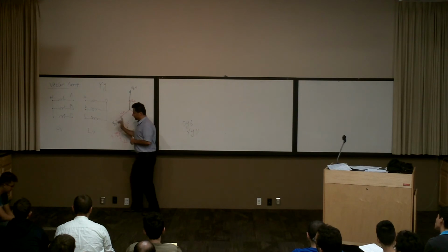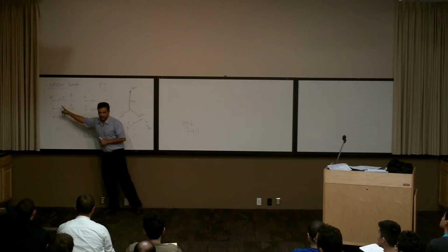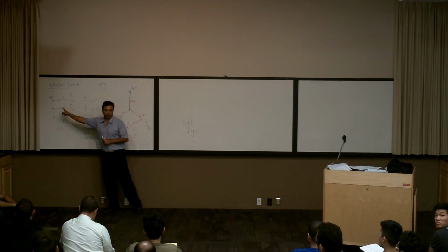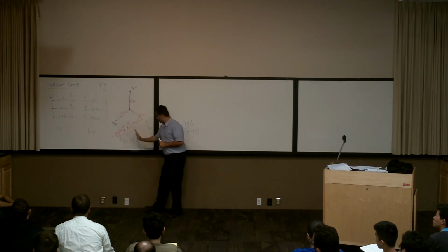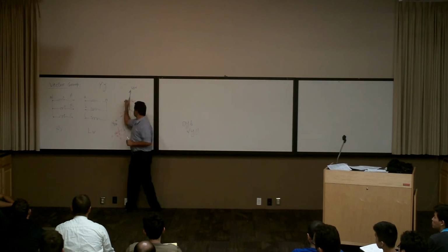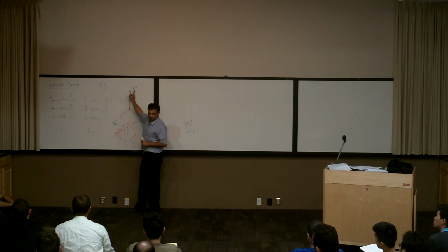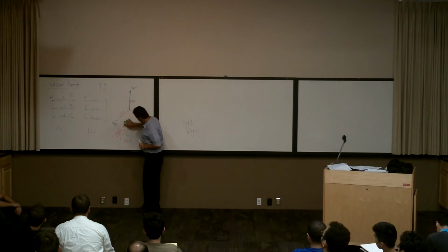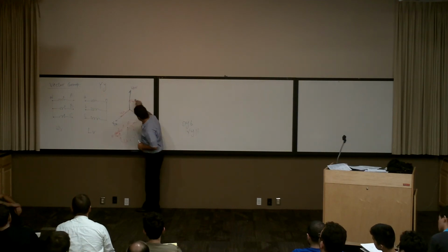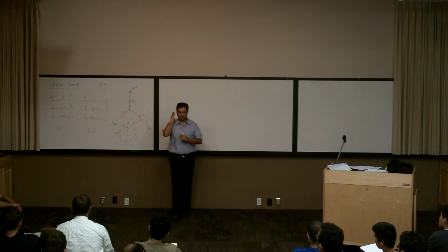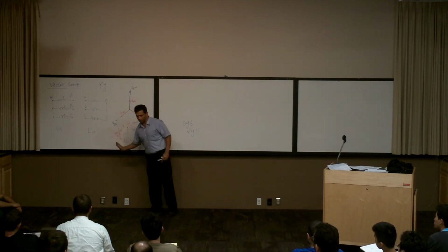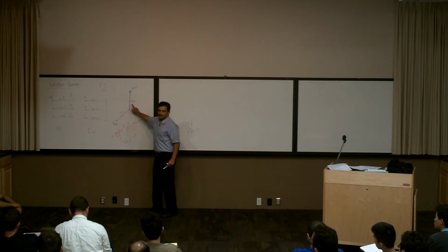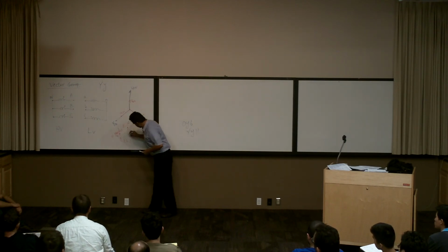The minute hand represents the high voltage vector, right? So for example, in this case, I put VAN, the blue one, the big one, here. Where is the second one going to be? Always we put the high voltage on the number 12. Now we'll see where the little hand is. For example, in this case, the little hand is going to be like this.